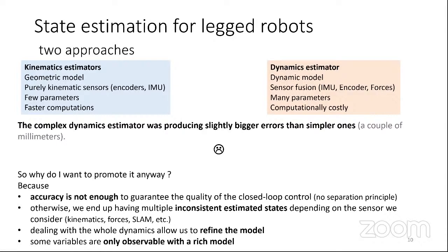In nonlinear control, you need to deal with closed loop dynamics, which is not necessarily stable, even if the estimation and control are stable independently. So properties like stability and smoothness, and maybe not being too sensitive to errors, are necessary to guarantee the quality of closed loop control.